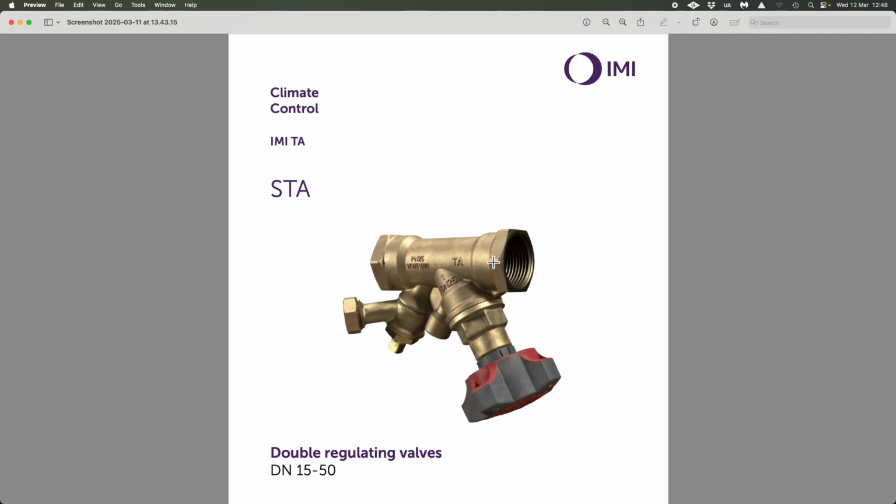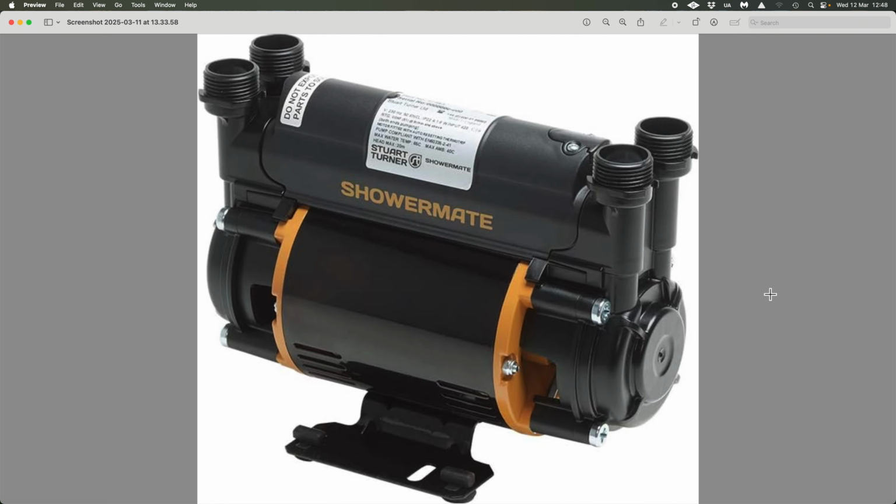If we decided that we were going to use an existing cold water storage tank in a 3-bed house that had a combination boiler put on, it's just got one bathroom with 1 shower, 1 bath, not used necessarily simultaneously, but it's there. You could install very, very simply one of these little showermate pumps, or not particular brand. I'm not sponsored by anybody here, so this is just an image that I'm used to. So one of these little units, and you could just pump.